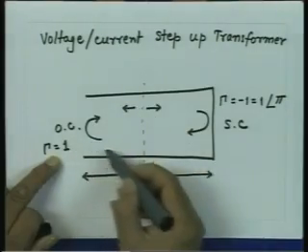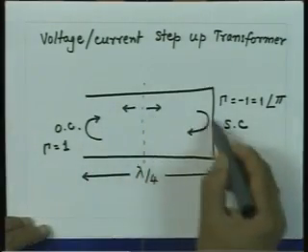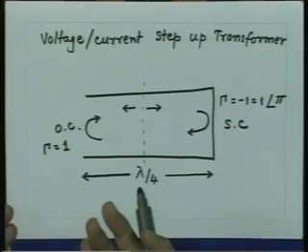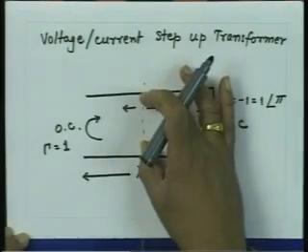This wave will grow in amplitude, and this wave will grow in amplitude in exactly the same way, and the standing wave on this line will grow, because the two waves are equal in amplitude and are going exactly the same way. So, we will develop a full standing wave on this line because of a small induced voltage at this location.